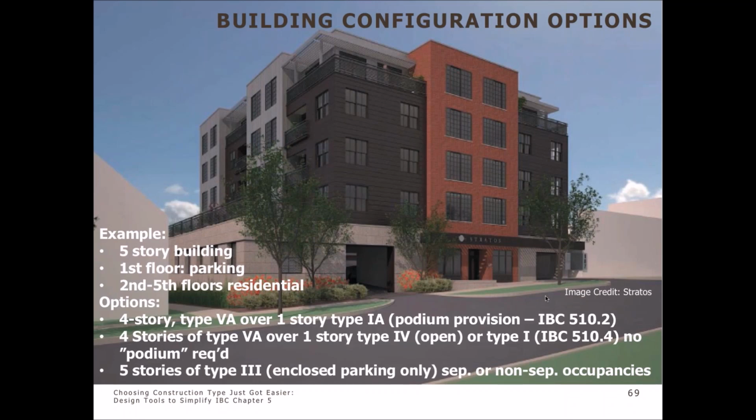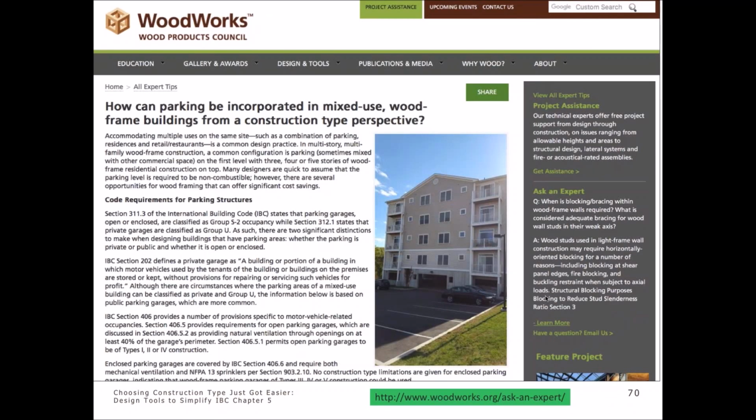The code does allow that if our parking level is enclosed. So that would be another option. And this post on our website, you can see the URL at the bottom there, discusses some of the unique code provisions specific to mixing parking occupancies with other types of occupancies in wood frame structures.